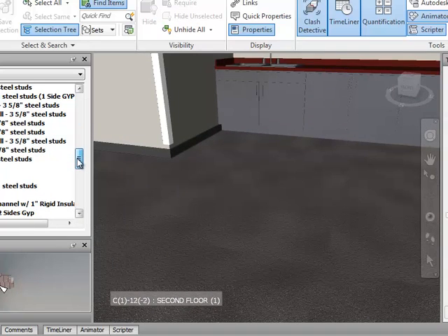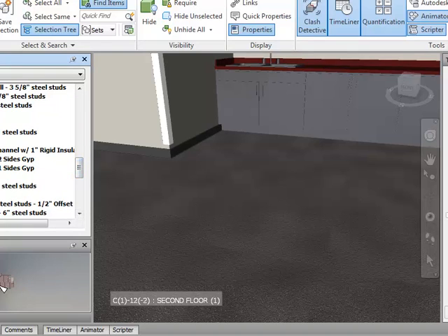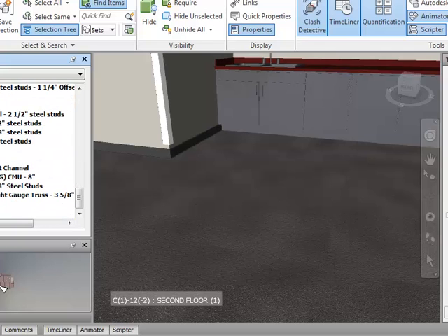The concrete, obviously, that's Division 3, right? Furring walls, that's going to be part of drywall. 4-inch studs. Yeah, so gypsum board or drywall, same term, right? Fence, if it's an interior fence, would most likely be Division 11. Like I said, with Divisions 10, 11, 12 there are some things that are a little gray in which one they fall in. It's tricky sometimes figuring it out, especially if you're not as familiar.